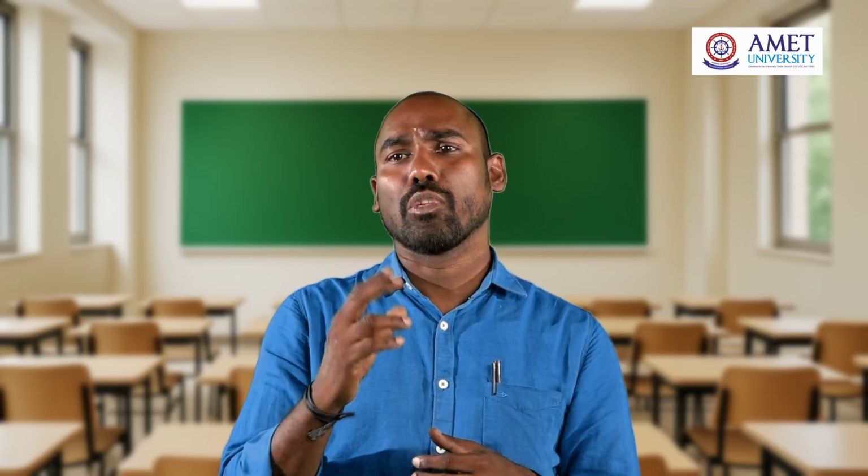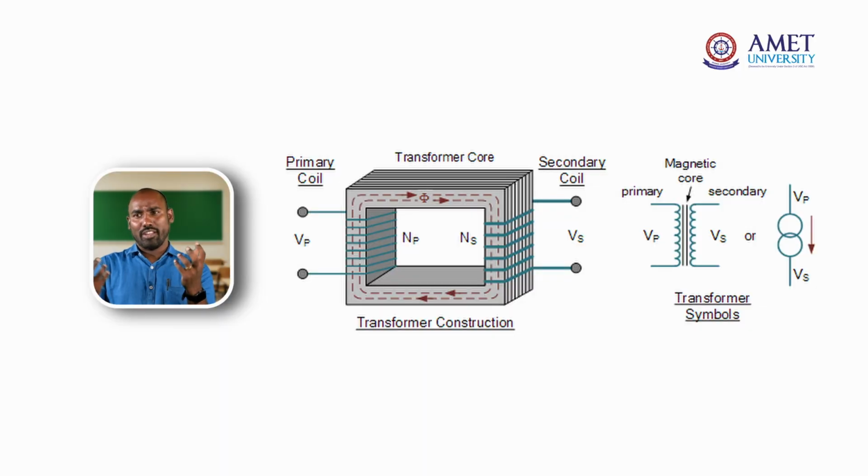Now come to the setup of the transformer. In a transformer unit, two important things are there: one is the core, another is the coil. The coil, as I mentioned initially, carries the primary AC current. We have two windings on the coil, which are fixed on the core. Normally the core is rectangular shaped and made of soft iron.